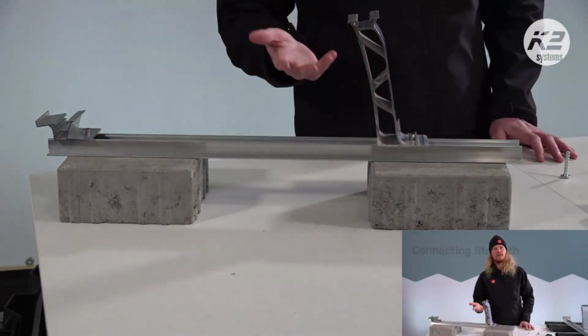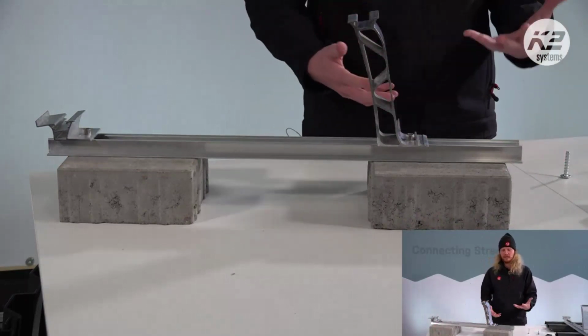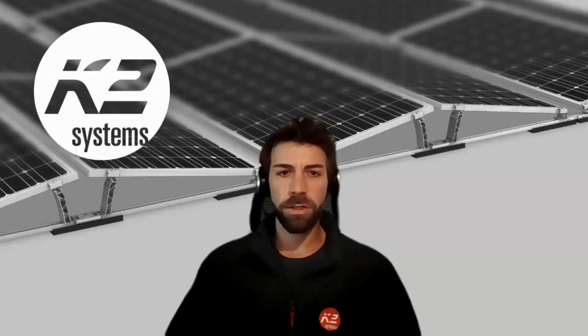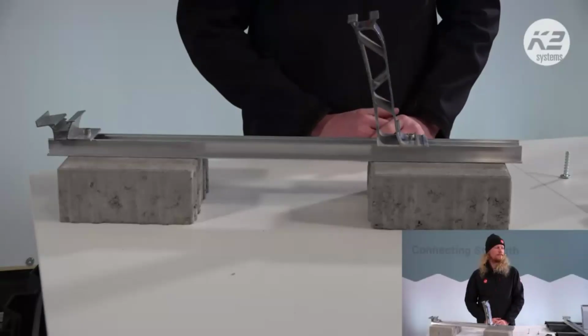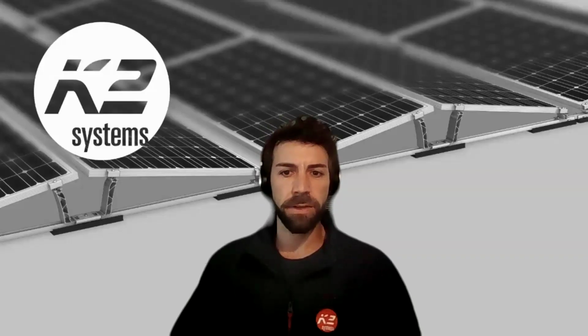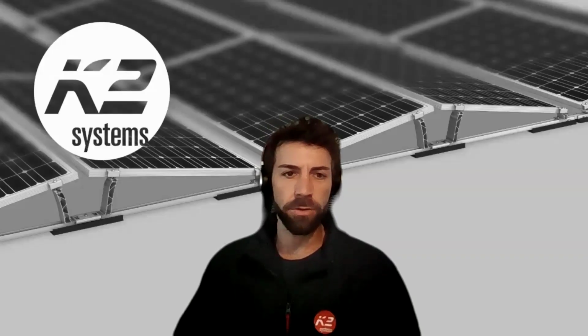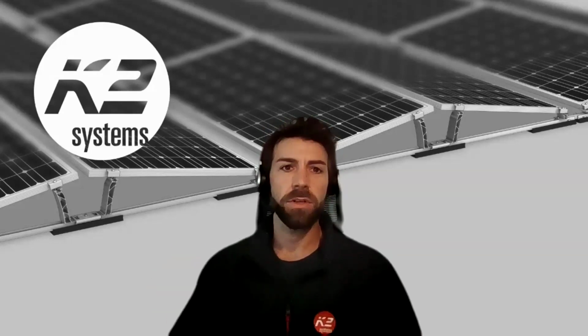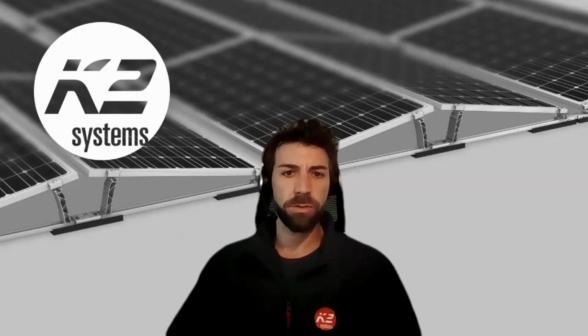But then as Roman is saying, and Roman, correct me if I'm wrong, this is included in the calculation of BASE as well. Yeah, that's why, as you said, if in case you're getting confused, you have a 10 centimeter block and you say, hey, nice, it's fitting, the roof is strong enough. And you say, okay, now I want to put a 250 millimeter stone on it. And now you get way higher ballast values. That's the reason why, because there's a factor calculated on top. You get more wind underneath, so you will need more support to hold it down.